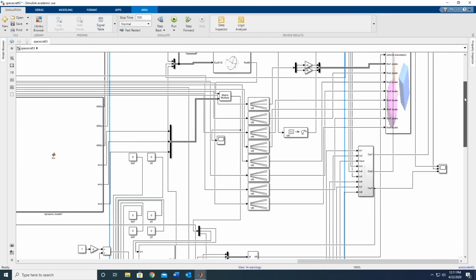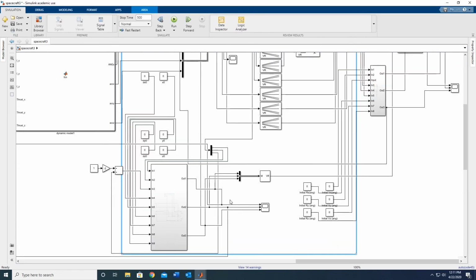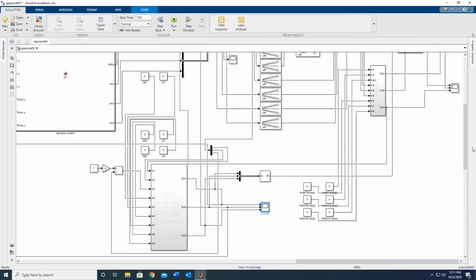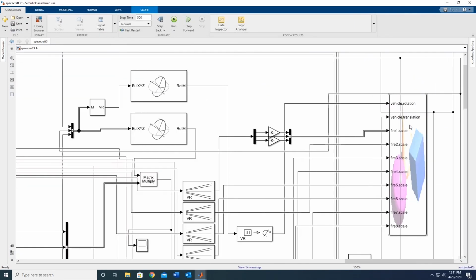All right, so then what I do with the positional accelerations, once they're stitched with the real-world coordinate frame, is go ahead and double integrate them to give me position values based on some initial conditions. So this way I can add initial conditions to the system. And I have these, by the way, for both the angular values and the positional values. And then I scope them, so I make a scope that allows me to look at them in this space. And then finally I feed them into the translation of my animation.